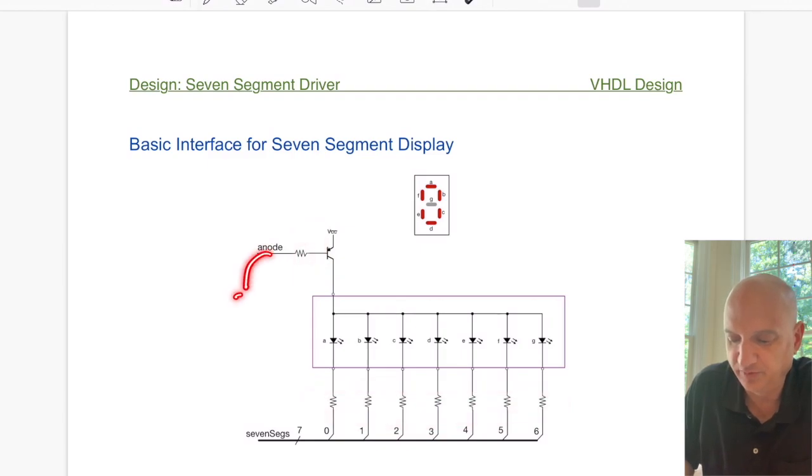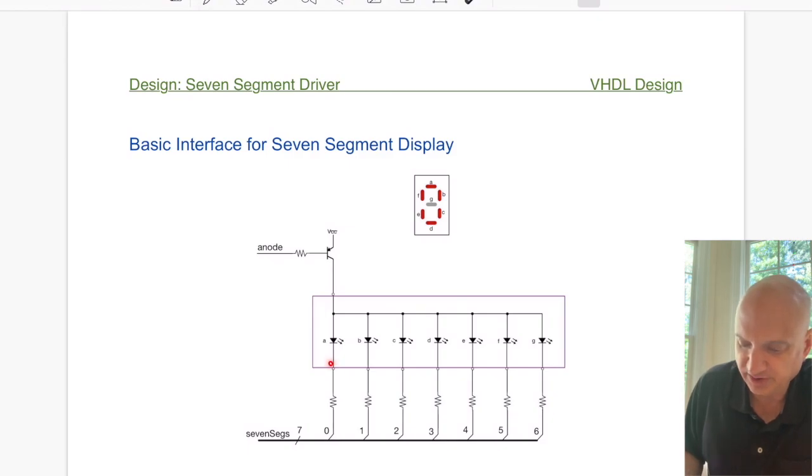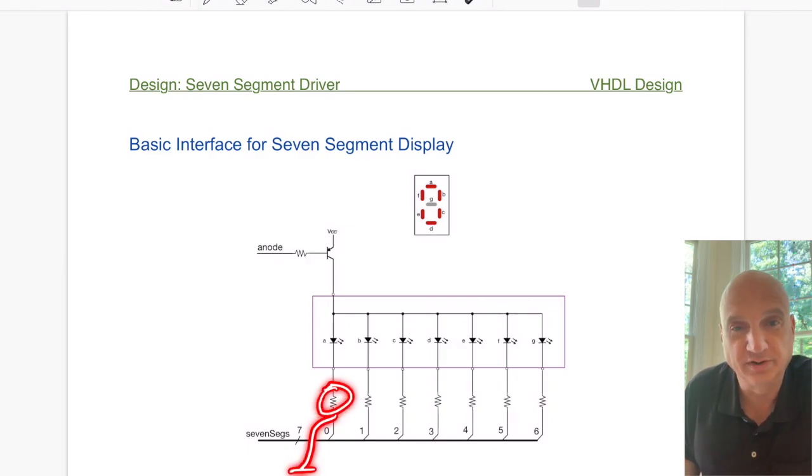So remember, if you short this to ground, you're shorting power to ground. So you have to have a resistor to actually help prevent that from damaging the pin. Same thing here, when you short this to ground, right here, well, we would short it here. We go through a resistor in order to make sure that it doesn't overcurrent the input and damage the input.